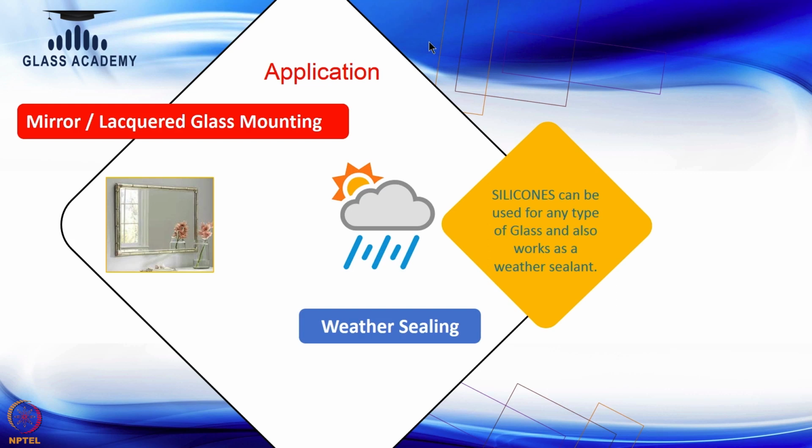Then another part of silicone usage is related to the weather. As we discussed, in this category paint is involved, and the silicone involves some adhesive, and mounting tape also involves some adhesive. So all these adhesives must be weather compatible. It means there should not be any impact of inside or outside weather conditions. Like in rainy season, if some moisture is coming, it should not get peeled off, it should not get detached from the substrate or from the mirror part. So the silicone used in this category must be a weatherproof silicone. That is again one considerable element of the silicone specification.